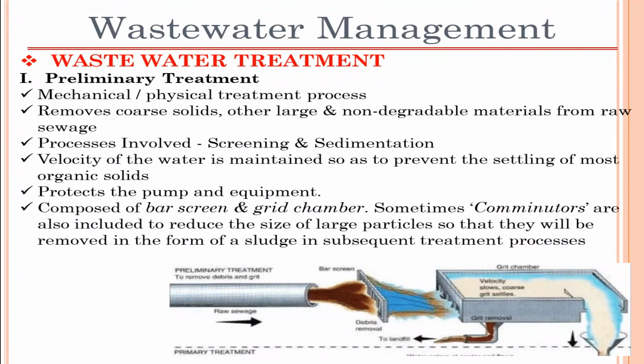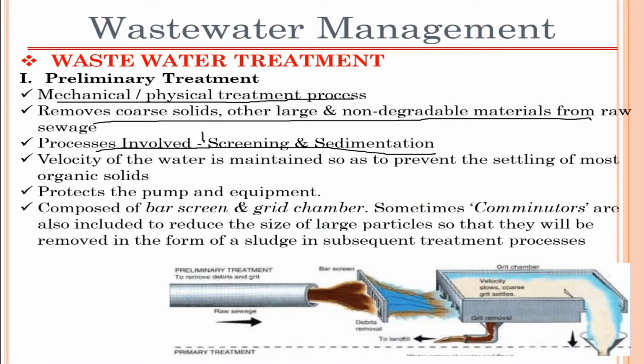So starting with the wastewater treatment, what it talks about is the preliminary step. It is nothing but the mechanical or physical treatment process. In this, the larger particles are removed. Coarse solids and other larger non-degradable materials are removed, and the process involves screening and sedimentation.